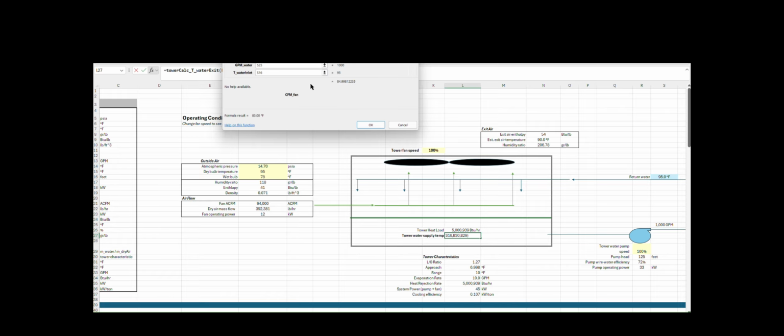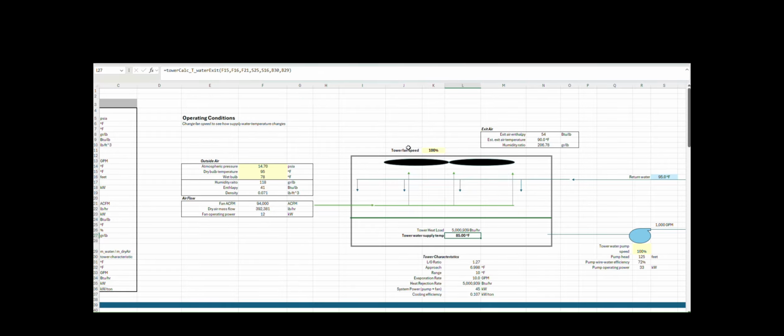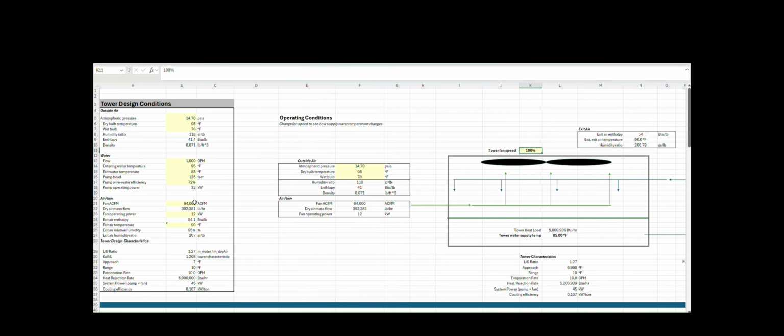And it also lets you segregate how much of that CFM is dry air versus water vapor. Because anytime you're doing a mass flow of air times an enthalpy difference, you need to use the dry air mass only. You don't use the mass of water vapor in that air. So that's the first thing that the macro does. We're getting, and by the way, we're getting CFM from the percent speed that it's running at times the rated CFM.